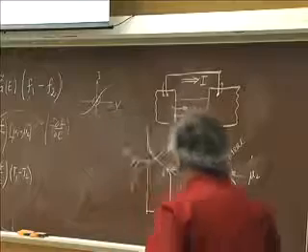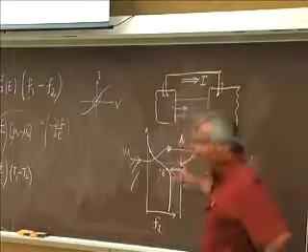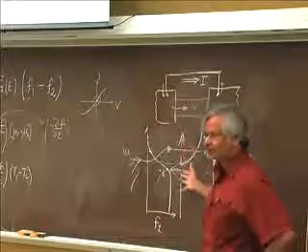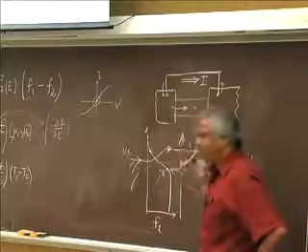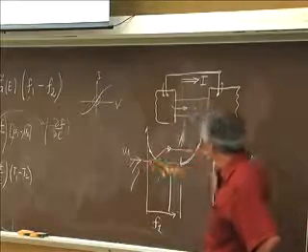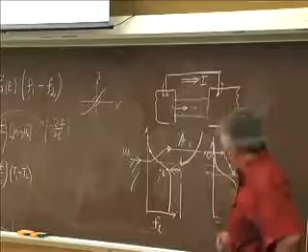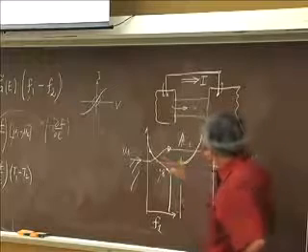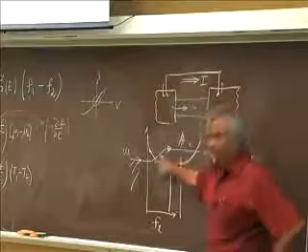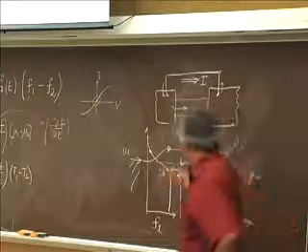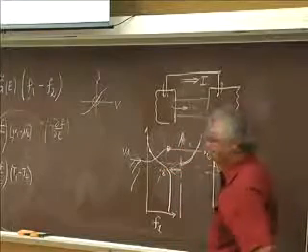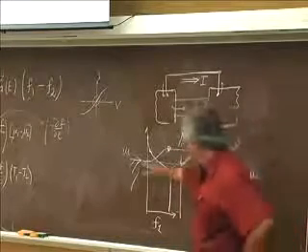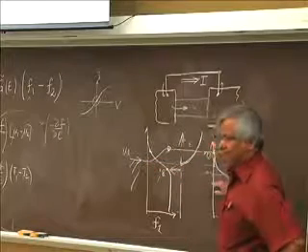Well, I said it happens in the contacts. And the point I'm now trying to make is that with these N-type conductors, it is not all heating. One is getting cooled, the other is getting heated. But then it is getting heated more than it's getting cooled. Why? Because, of course, in order for electrons to be flowing this way, since the temperature is the same, μ1 must be above μ2.